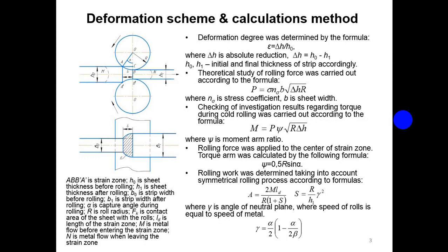The deformation scheme and the method of calculation of process parameters are presented on this slide. We determined the deformation degree, absolute reduction, yield strength of material, rolling force, torque during cold rolling, and rolling work.